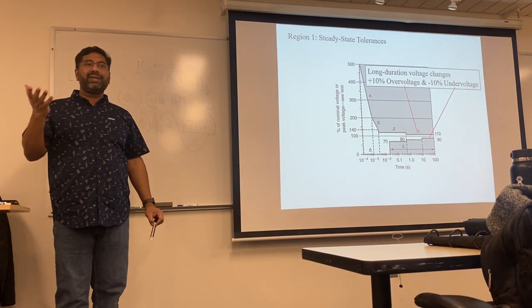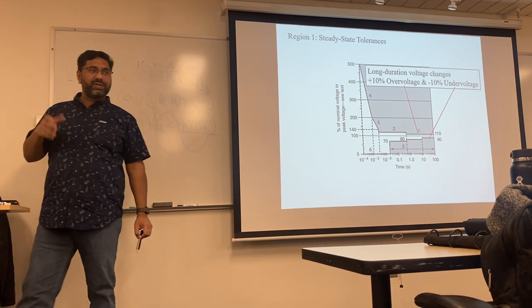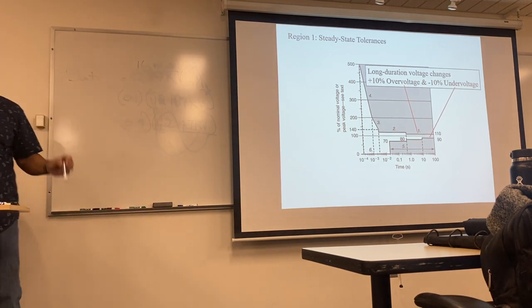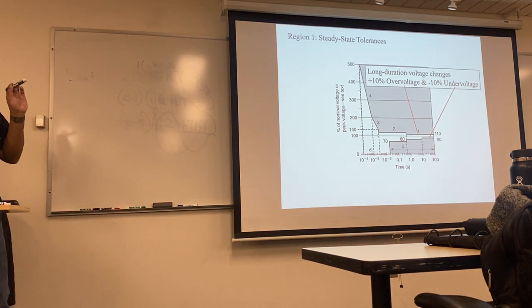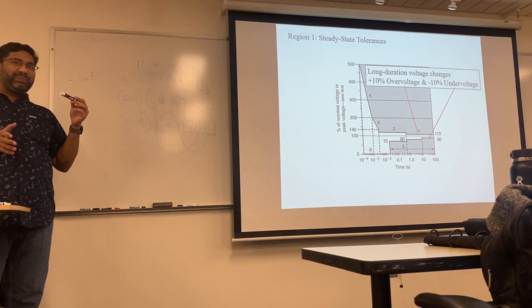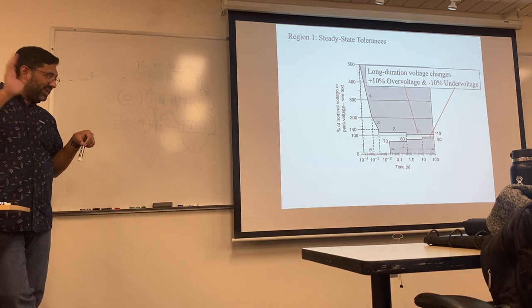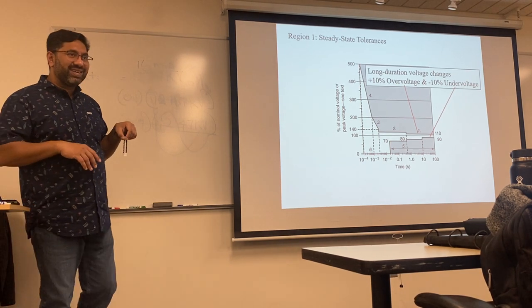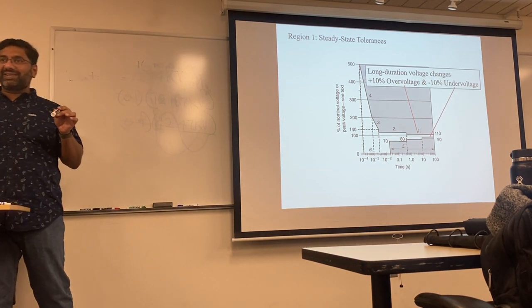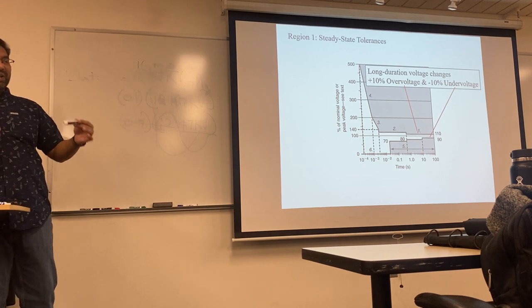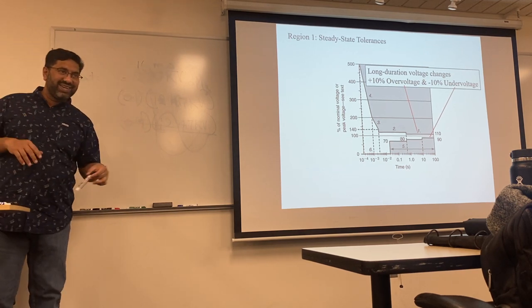It's literally called a fast fuse and a slow fuse. So, depending on the application, what are you trying to do? In a lab, you're trying to get the output. You don't care for the PSU's infrastructure, so use a slow fuse. You're working in an industry, you want to protect the equipment, use a fast fuse.